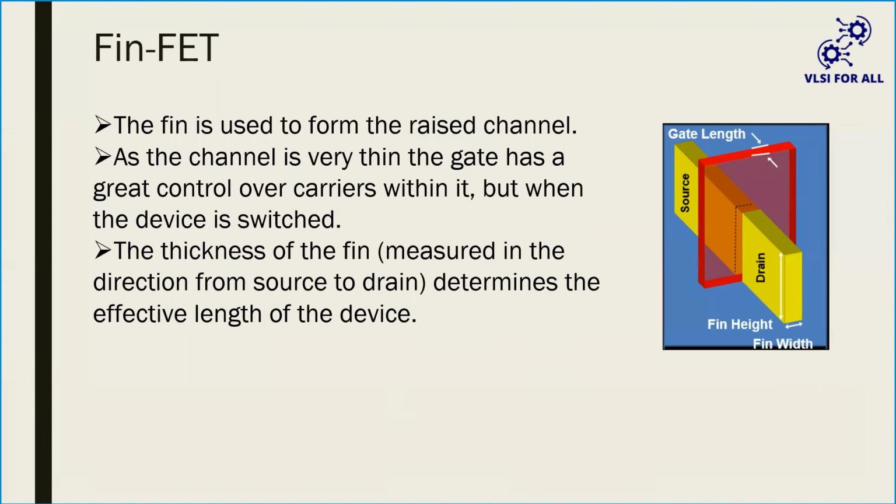But now in FinFET, you can see the gate from other directions as well: from the left side, the right side, and the top, not the bottom. Team, remember, not the bottom. So we made the source and drain construction in such a way that the gate covers the source and drain regions in all three directions. I repeat, three directions. And this red color is just like a fish has fins, so we call it FinFET. The gate is in a fin's shape.